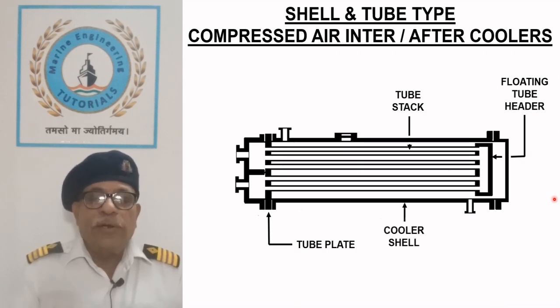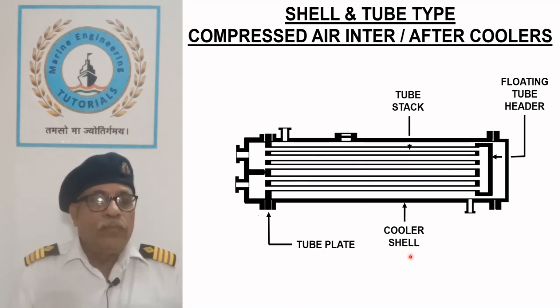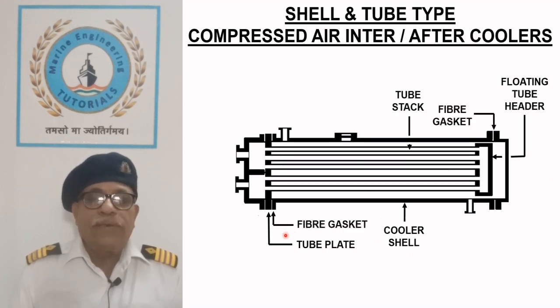Tube stack is inserted into the cooler shell. Fiber gaskets are placed between both ends of the shell to seal against the coolant leakage.